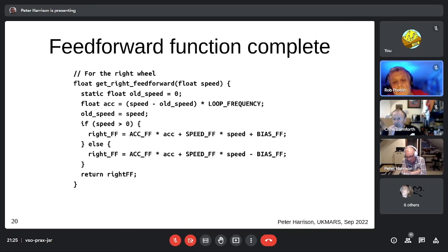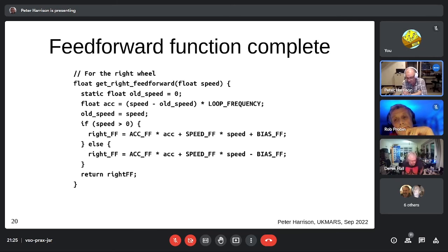certainly one of the things that if you were on a line follower, if you were plotting the course and recording it as segments with different curvatures, then certainly a feed forward term based upon the anticipated rotational angular velocity during that turn would be a good thing. It would have the same benefits as it would for forward motion. But in terms of the actual sensor value, I suspect not, because the error that you see is determined by how fast it goes and stuff. But on the other hand, do the experiment and let us know.